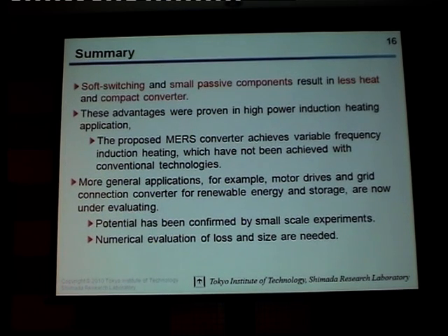So this is my last slide. I will conclude my talk. Soft switching and small passive components are key issues, and they result in less heat and a compact converter. These advantages were proven in high power induction heating applications. We can achieve variable frequency induction heating with small electric equipment. The proposed MERS converter achieves variable frequency induction heating, which has not been achieved with conventional technologies.